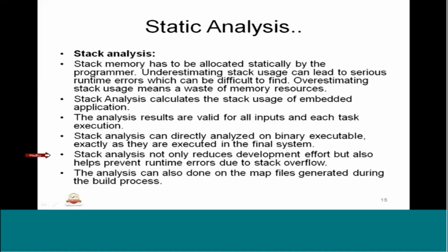And stack analysis not only reduces the development effort, but also helps prevent runtime errors due to stack overflow. So it's a very important aspect that at any time of the embedded software system or the program, we should make sure that there is no stack overflow during the runtime. So this also will be analyzed during the stack analysis of the embedded software system in the static analysis.